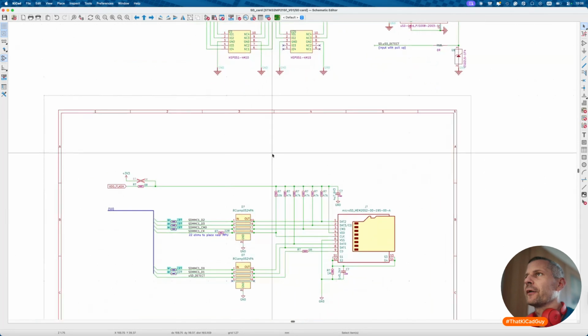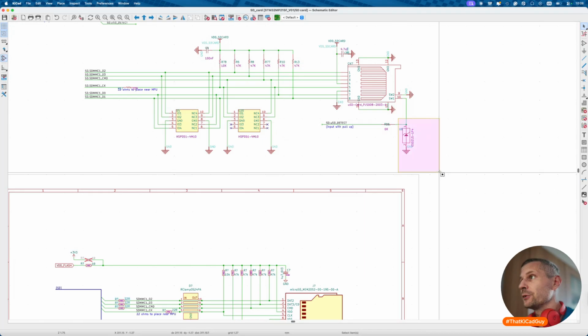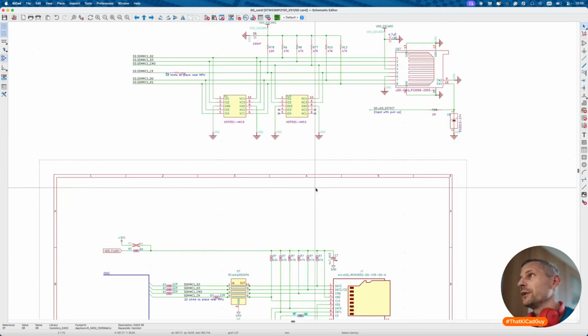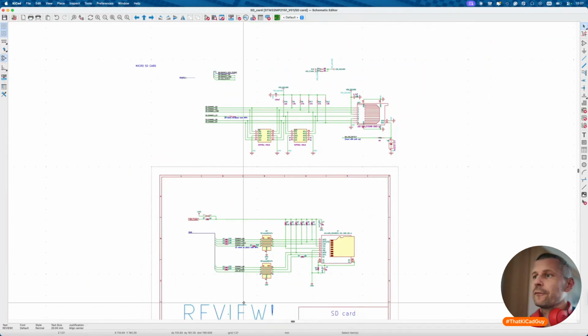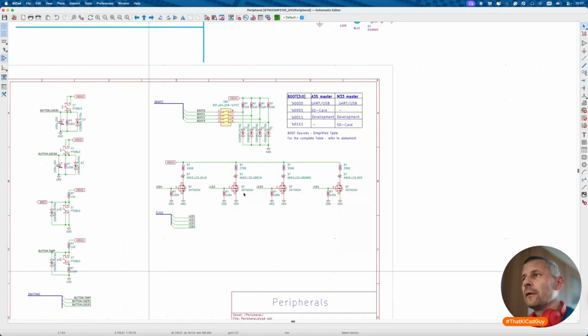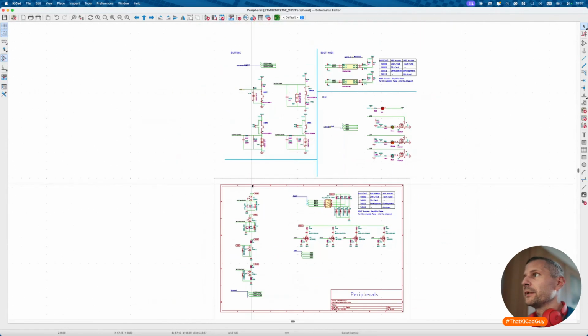Okay, there were 2 channels empty, so I placed the signal through it. If it doesn't work in the phase of PCB layout, I will use the discrete component. That's not a big deal. I kept the 0 ohm resistor here, which is not a big deal as well. Yes, so I think it's fine. Can delete it. Peripherals were reviewed a minute ago.